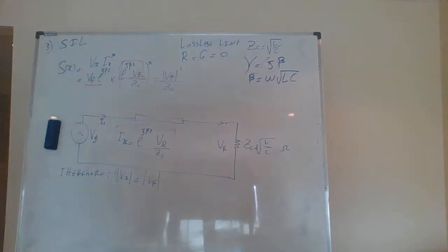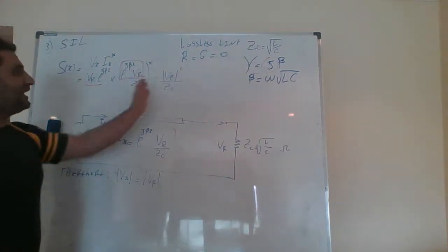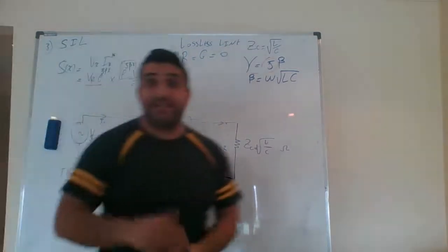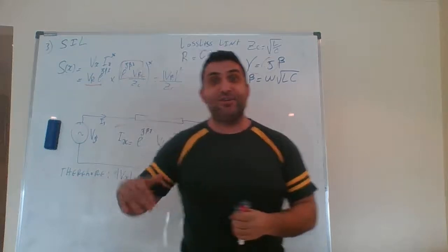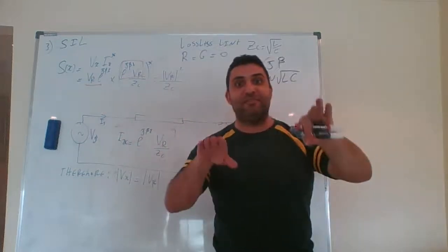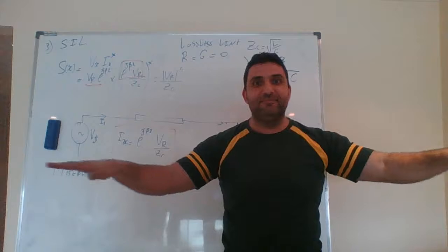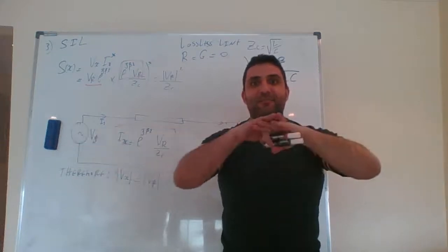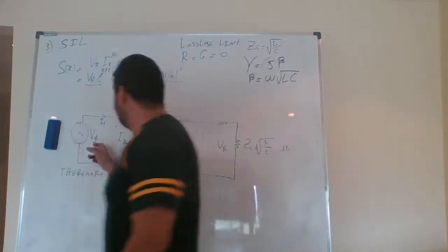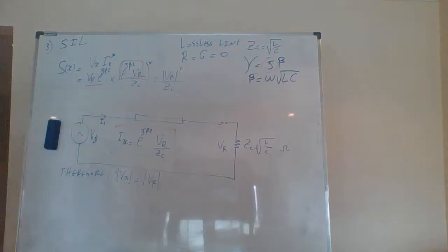And the reactive power, as you can see, is zero. The reactive power is zero because, like I said to you earlier, the surge impedance loading happens when the capacitive and inductive effects balance each other. Is that clear, guys? Is that clear? Or it's not clear?